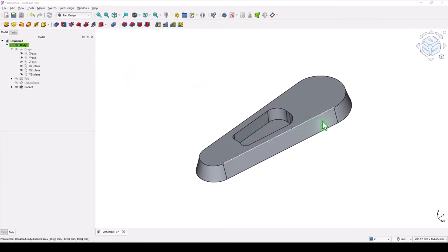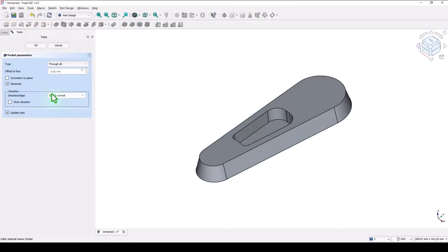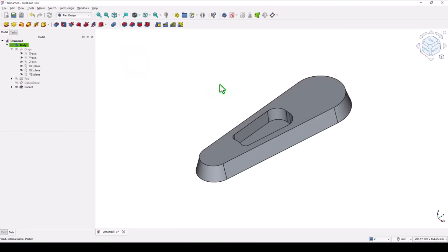close. Now we want to apply a taper like here, but for a pocket we don't have any taper. You see here we don't have any taper. Then we have to create our own taper. Here it was a taper of 15 degrees, and we place here the same taper.